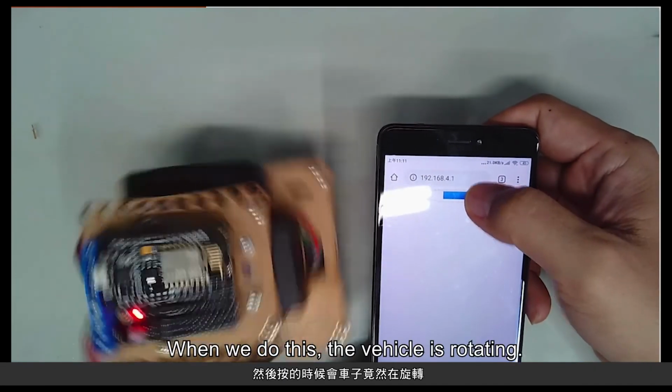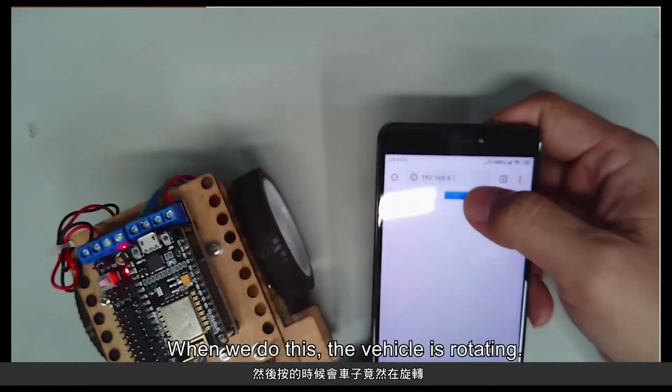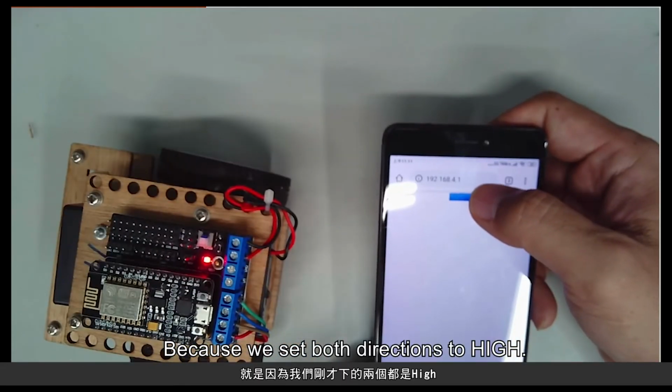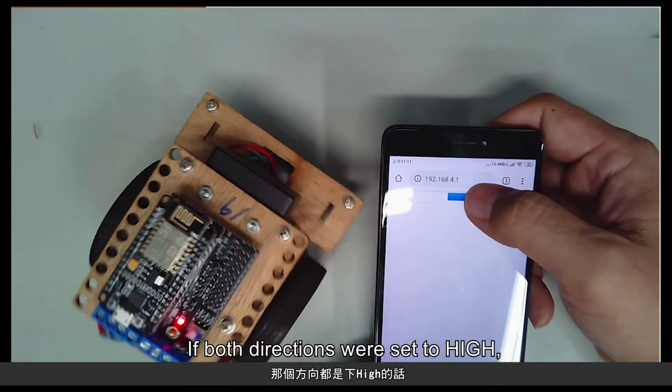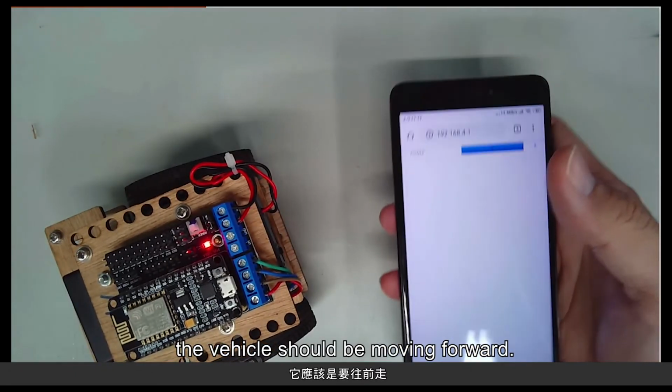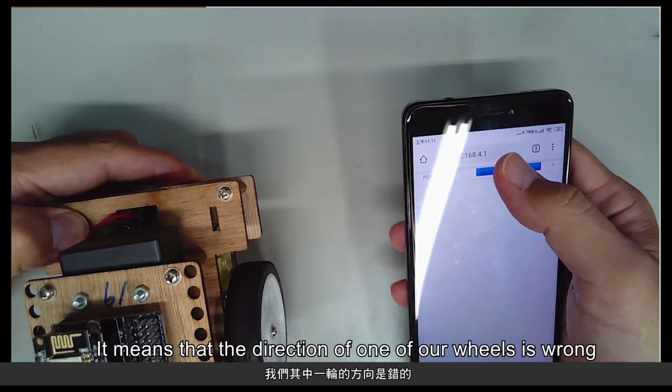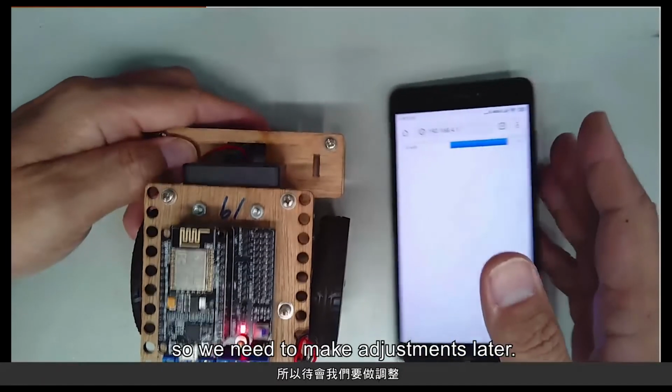When we do this, the vehicle is rotating. Why is it doing this? Because we set both directions to high. If both directions were set to high, the vehicle should be moving forward. So what does it mean? It means that the direction of one of our wheels is wrong, so we need to make adjustments later.